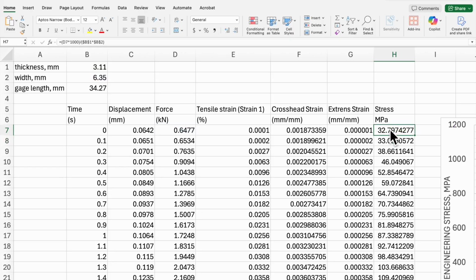And this is where units are important, right? If you had chosen to do this in base SI units, you would have wanted to convert the millimeters to meters, so you have meters squared. However, I left it in millimeters because there's a handy trick in tensile tests: a newton divided by a millimeter squared happens to be a megapascal, or MPa. That's always a good one to remember.